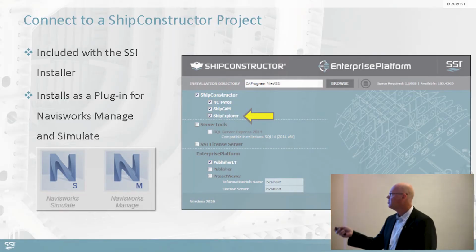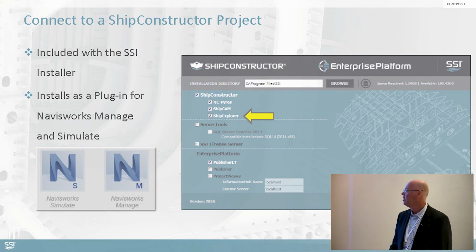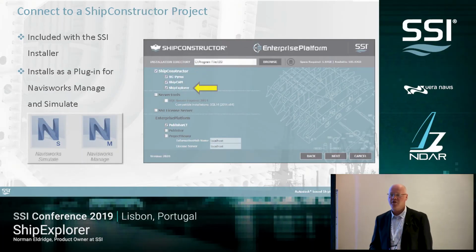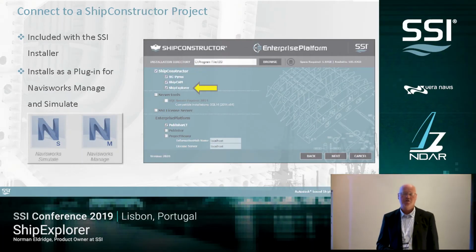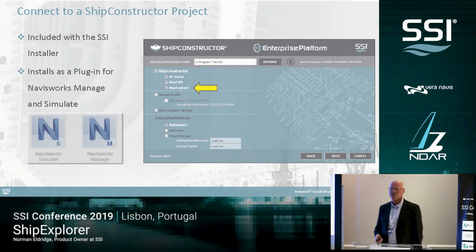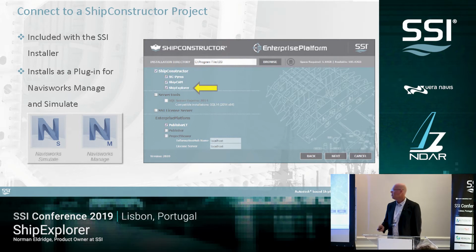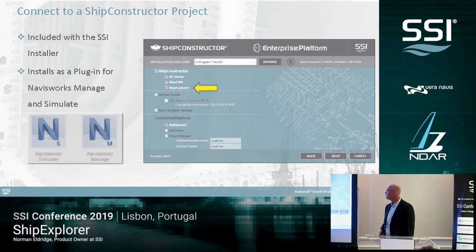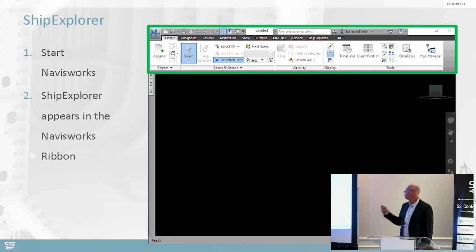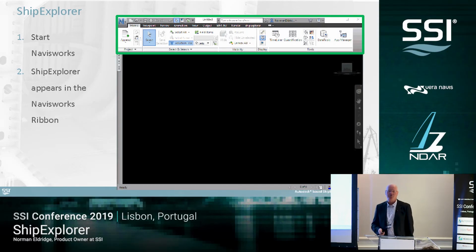You see it's included when you first install ShipConstructor. You just click on that box. It automatically sets up for Navisworks Manage or Simulate. It doesn't matter what order you're setting it up in. It puts the installation files in, and then it'll find Navisworks. Really easy to start. In the Start menu, you just launch your Navisworks, because it's an actual plug-in to Navisworks.